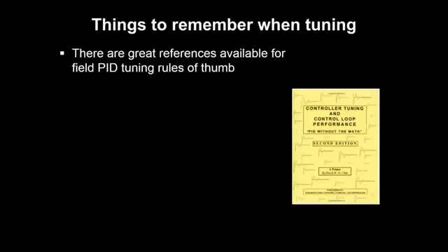But I will say from experience that when you have good resources like a field manual here, and when you've done your due diligence, coordinated with O&M folks, and made sure those safety devices were in place, this can be a very doable and fulfilling process, to go through a loop and do this tuning.